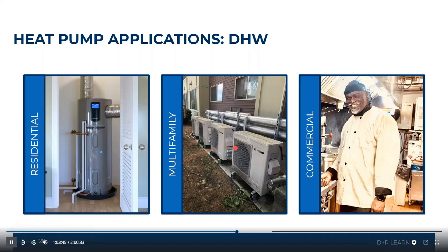Over in the middle image, we show several smaller heat pump systems, which, the term utilized in the industry is ganged, G-A-N-G-E-D. These systems are ganged together in order to provide domestic hot water for a multi-family building. So depending on the size of the building, the amount of units available, the load, the capacity, you're able to either remove or add, or in the industry, what's termed as ganged. You can gang additional units in order to supply capacity for your multifamily setting.